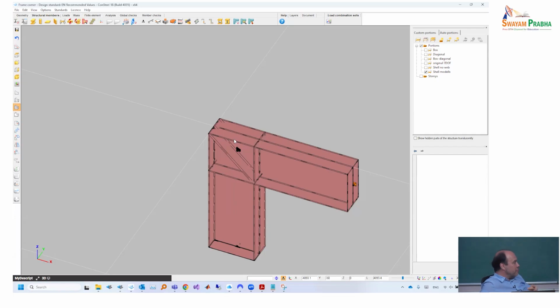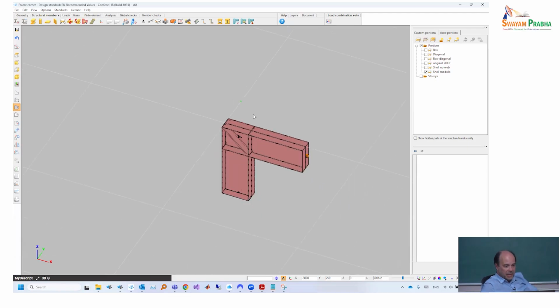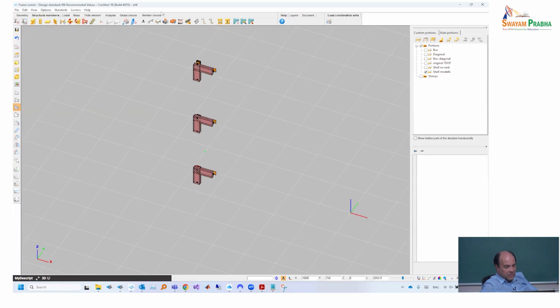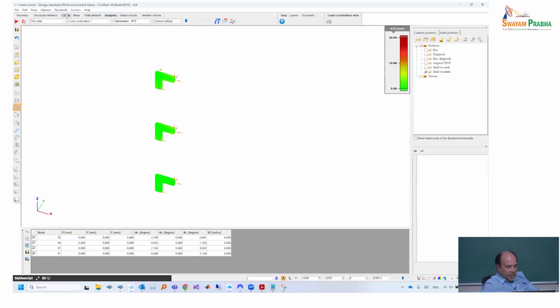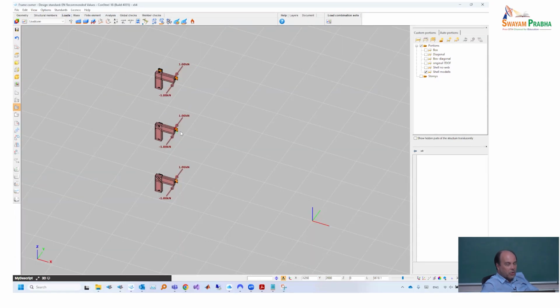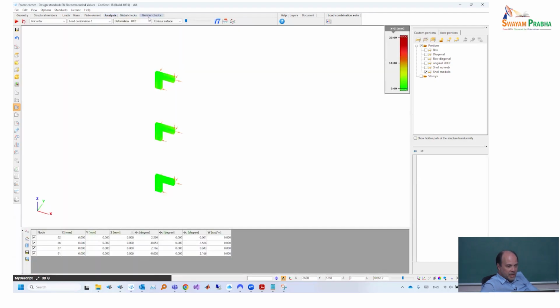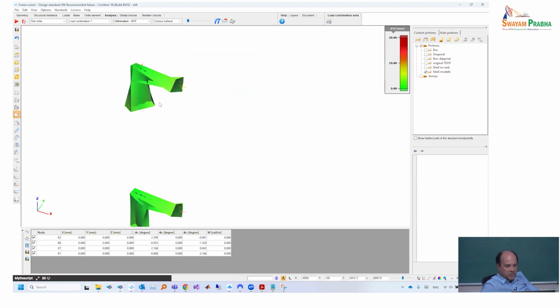And I'm not very sure that engineers are really aware of what impact it has. I think very often people believe that they put this diagonal only to prevent the buckling of the shear panel and not assigning any other meaning to that. But actually it's very interesting that this is not only about that. I applied on each of them a torque, so a pair of horizontal forces on the beam, and with shell elements I made a calculation to see how they behave. And actually it's very interesting.